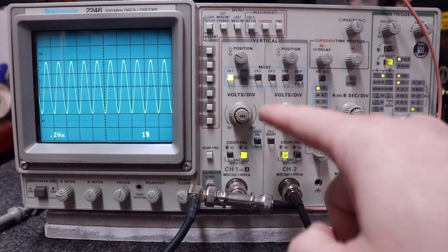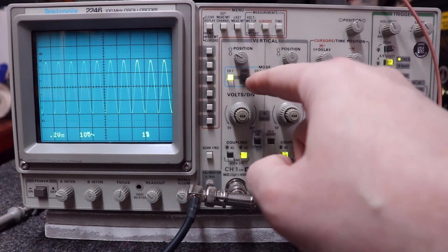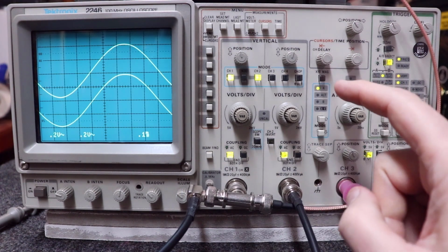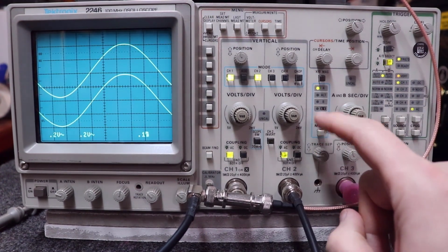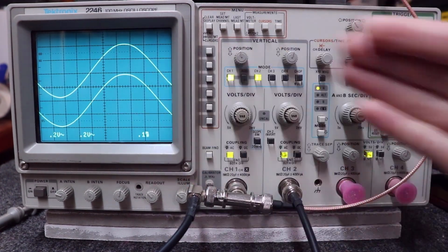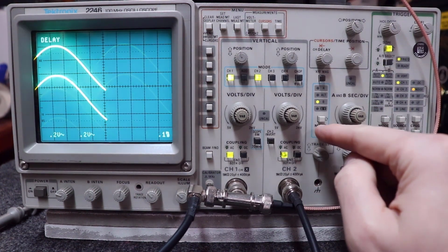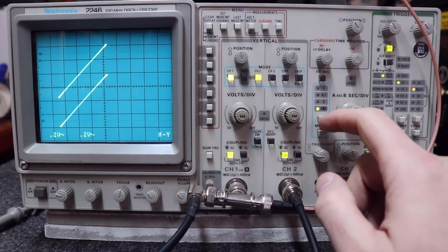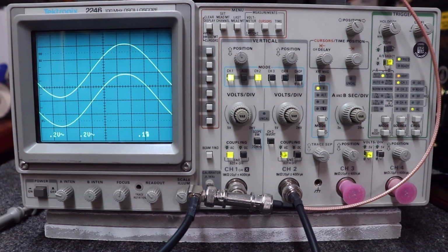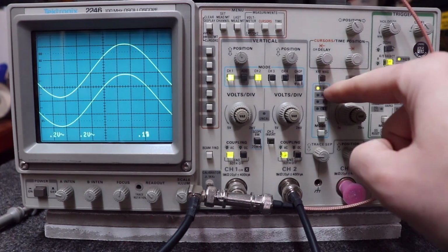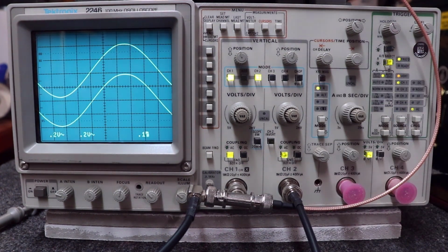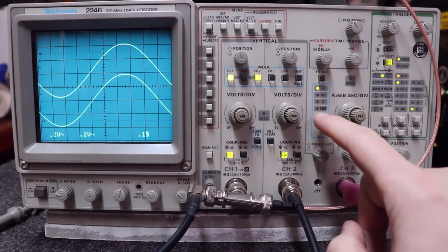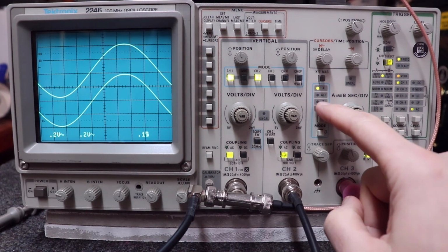Up next, say you've got two signals going on, channel 1 and channel 2 here. There's a little mode selector here. On the time division, you can go A, you can go B, you can alternate between them, or you can go X, Y, and I'm not going to show you that today. Really, 90% of the time you're going to leave it on A. In video 5, we will use the XY mode, and I'll talk about that. But both these buttons here do nothing more than move up and down in between those.